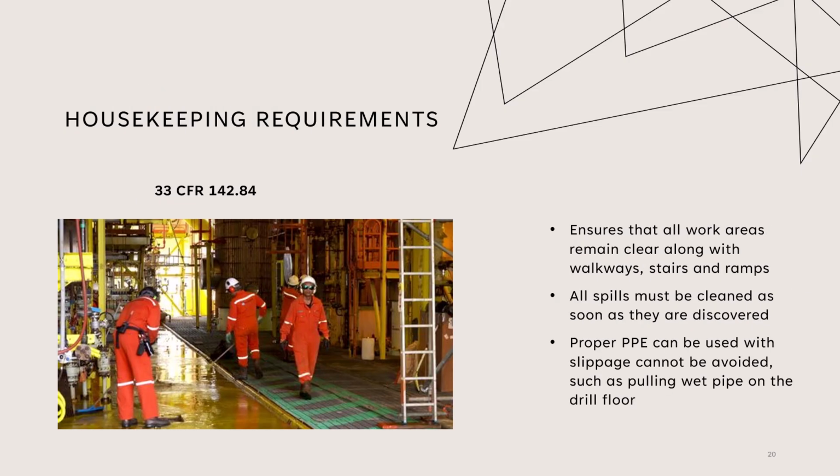33 CFR 142.84 is housekeeping requirements. It ensures that all work areas remain clear, along with walkways, stairs, and ramps. It states that all spills must be cleaned as soon as they are discovered, and proper PPE can be used when slippage cannot be avoided, such as pulling wet pipe on the drill floor.